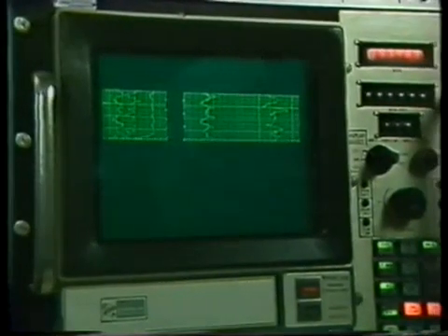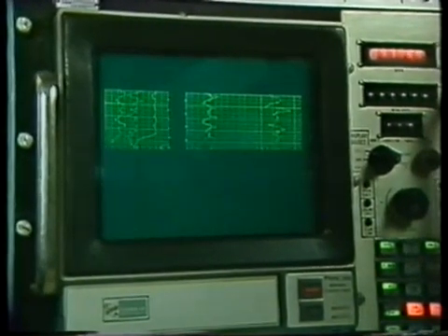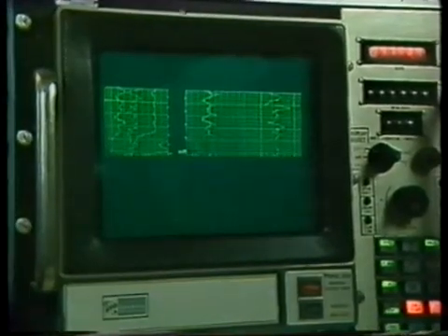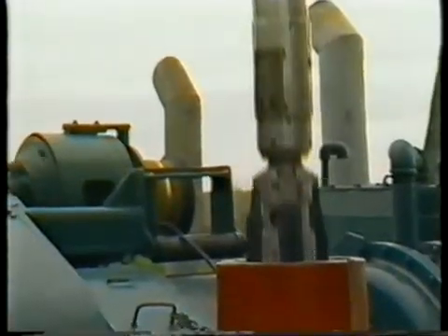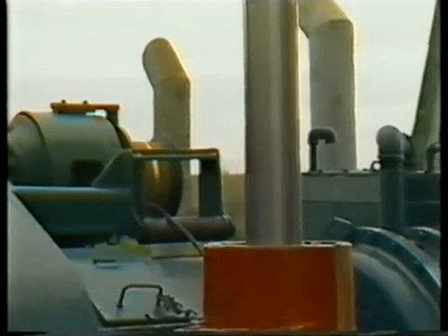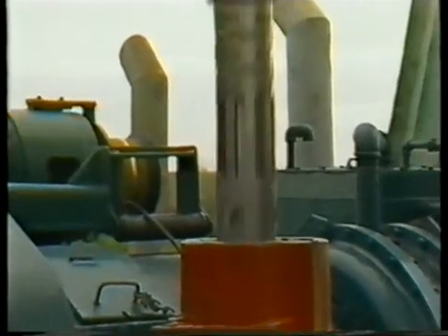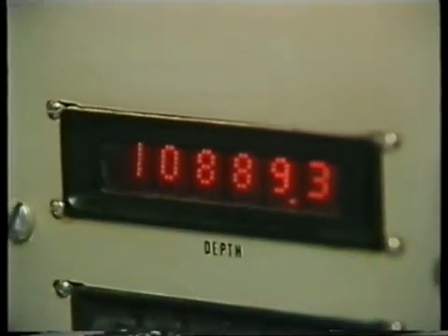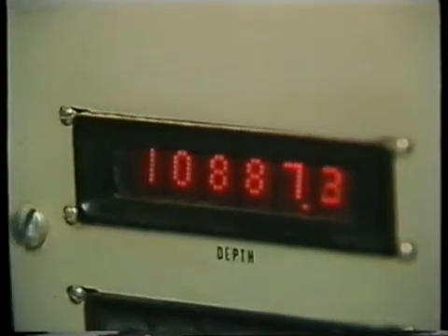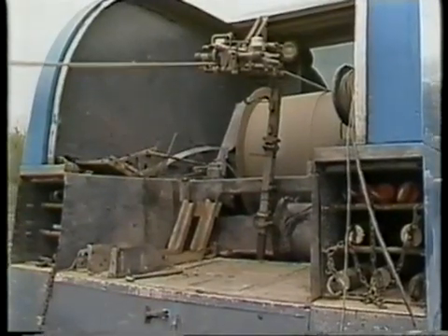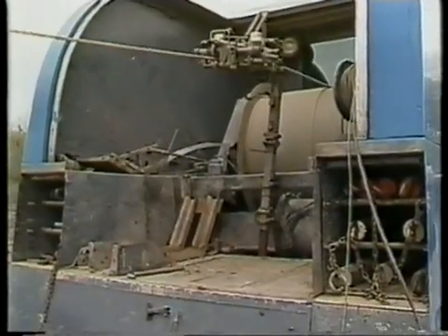Sometimes, in problem holes, logging going down the hole may ensure that some data is obtained in case problems are encountered. The speed at which logging is carried out depends on the logging tools in the string. Each tool has a maximum speed at which it can be run. In general, the slower the tool is run, the better, although, of course, practical aspects such as the cost of rig time must be taken into account.